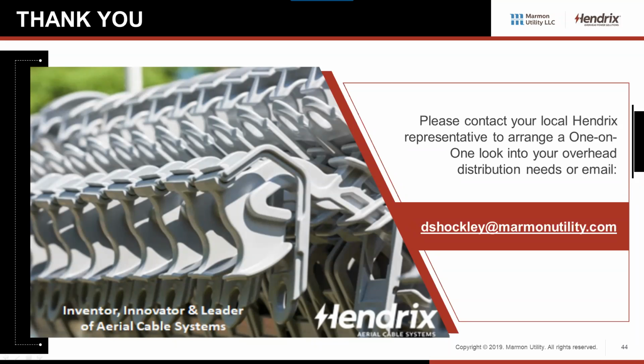Can you talk about some of the lightning protection requirements for spacer cable and the benefits of using spacer cable in high lightning prone areas? Well, our normal recommendation with regards to lightning arresters, the rule of thumb, is that any place you've removed the covering, we recommend you install lightning arresters.